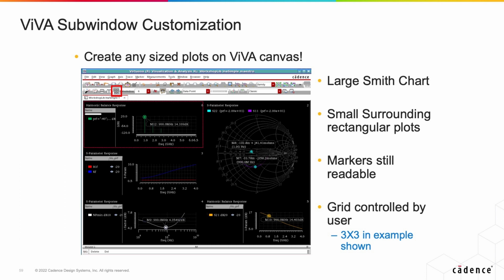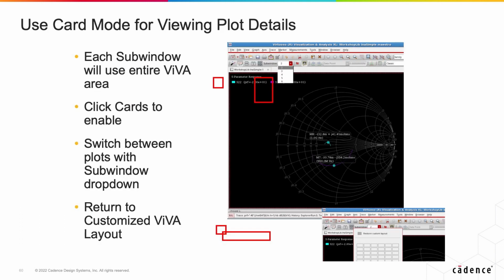reports. And the other thing is, you can save this grid and this custom template as part of your Maestro view. So when you're in Explorer or Assembler and you're running a simulation, then you say, I want this custom plot, and then you plot it this way, and then you save the Maestro view and you call it My Test 1 or whatever. Next time you open My Test 1, the plotting will be saved because you called it something. And for one Maestro view, you can have even 3 types of plotting templates. Maybe something for trans, something for S parameter, something for harmonic balance.